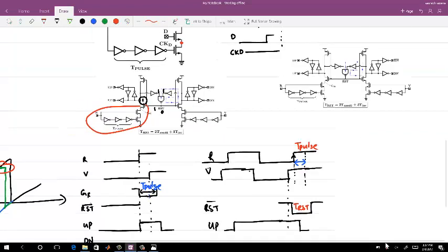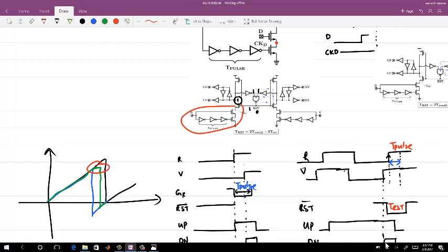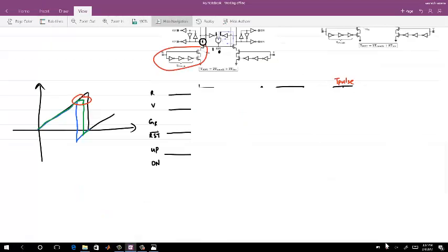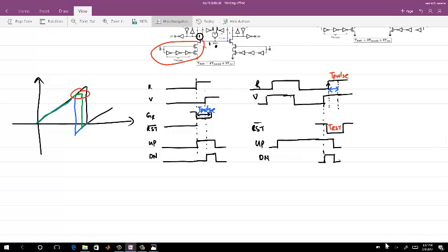But this is again dependent on all your pass transistor logic. So leakage and other things will be important for the frequency which you are considering. In no way can you remove that delta, other than T pulse equal to some very specific value; you will have a flat region coming to zero and going back. So these are the three standard phase frequency detectors which are used, and you can figure out what suits your design best depending on frequency, power, and all.